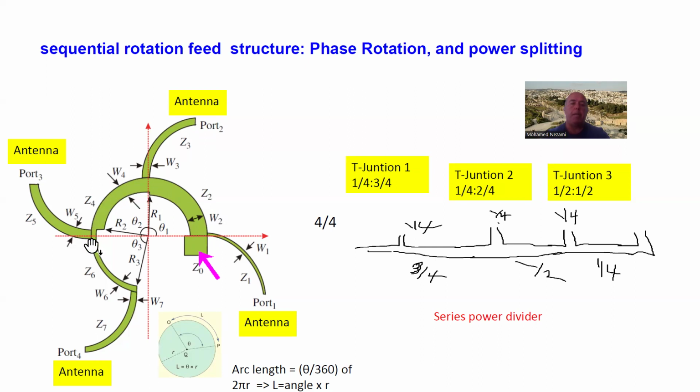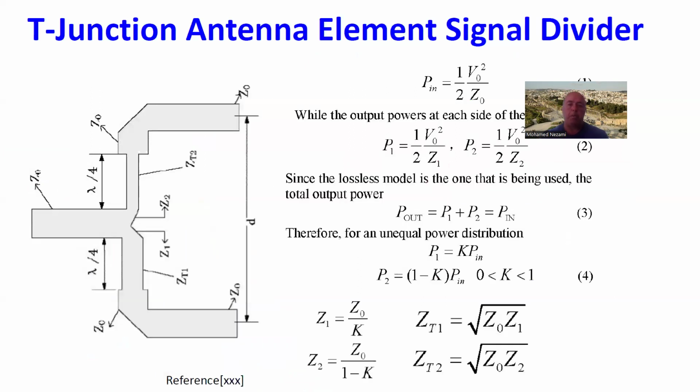And once you find the impedances of all these lines, you then go to a microstrip calculator, or the LineCalc in ADS or any other tool, using whatever substrate you're using, to find out the width corresponding to that impedance.